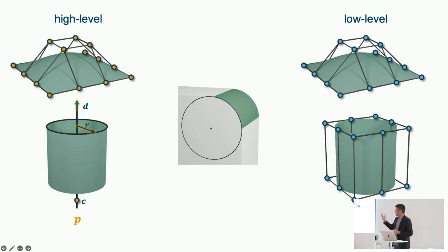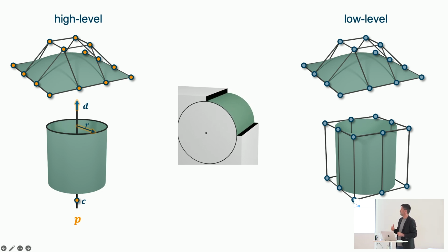Then we also realized, unfortunately, that doing just that alone is still not sufficient. For example, if you have such a rounded-off edge, and you start moving the center of this cylinder that defines the radius of this rounding, if you start moving this around without taking care of neighboring surfaces, you again start breaking the model.